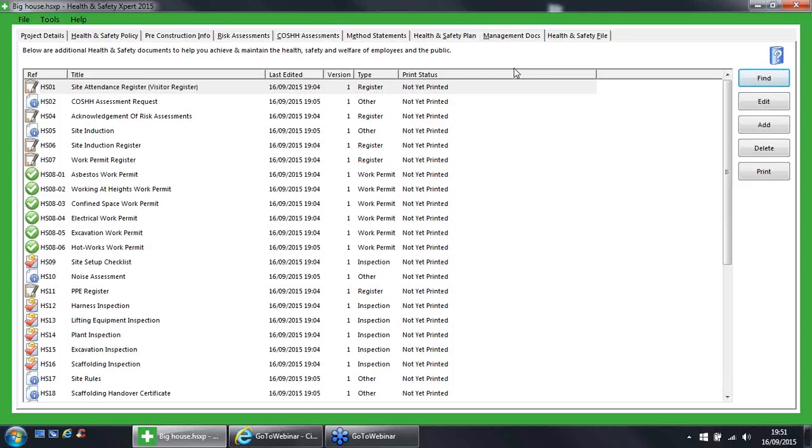For those of you who don't know, now all domestic work falls under the same criteria as commercial work for notifiability. So there's no longer the fact that small domestic jobs aren't notifiable. All jobs can be notifiable. What defines it as notifiable now is basically the duration. Typically, once a job goes over sort of 3 or 4 months, you're into the realms of it being notifiable. Okay, if you've got a small lean-to extension that's a 4-week job, that's not notifiable. If you're building a 2-story extension that's a £500,000 job because it's on the side of a mansion, it's going to take you 6 months, that is notifiable under the new rules.